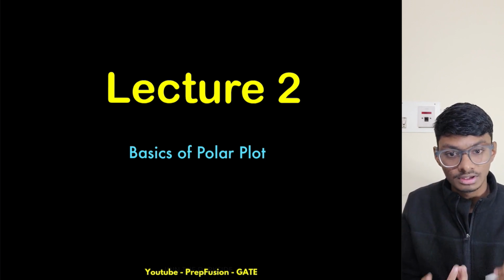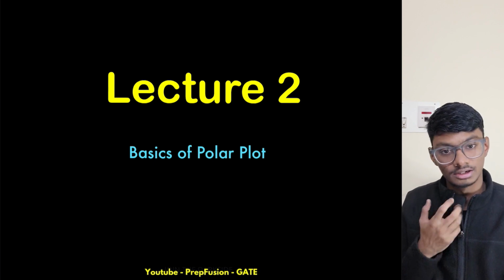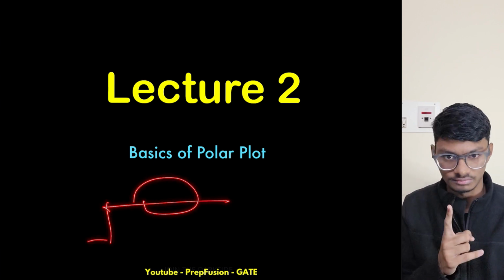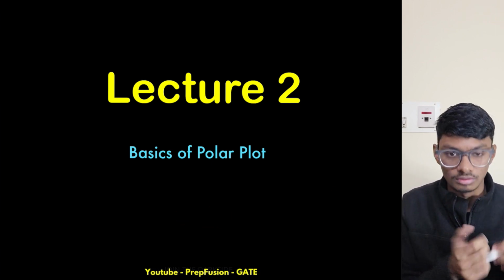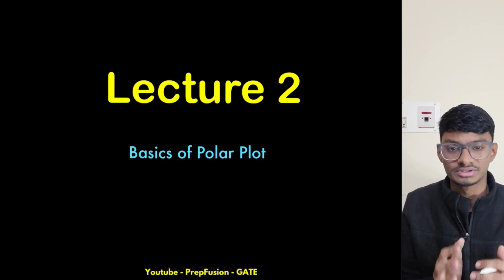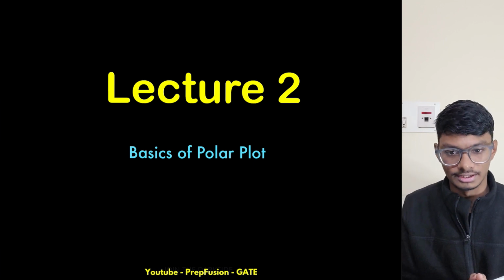Even though my system is stable, my input is oscillatory, hence my output will also be oscillatory. In time domain, we gave a unit step and the output settled to 1 at steady state, after some transient part. All those things we measure in time domain analysis. So I hope you got a brief idea about frequency domain analysis.